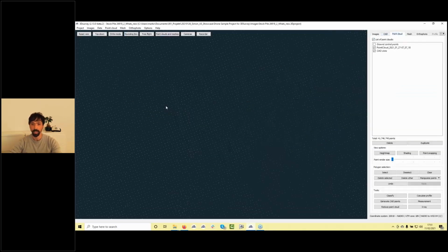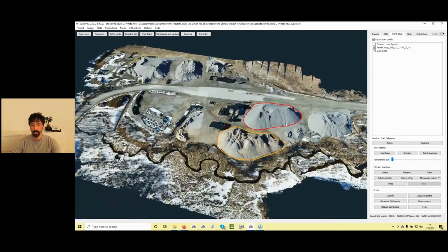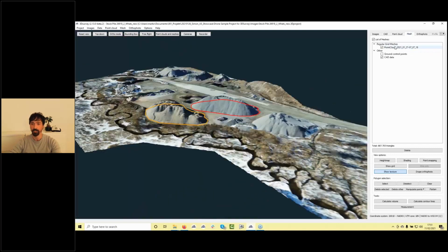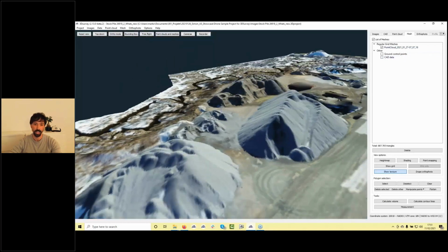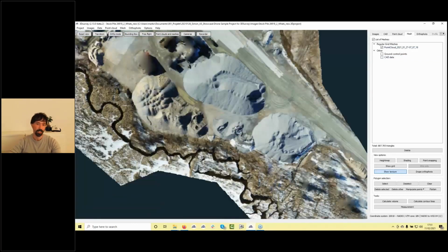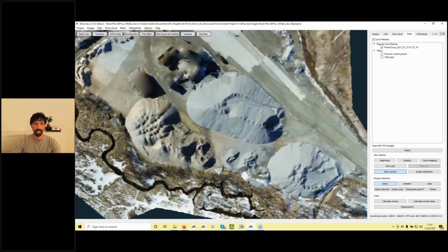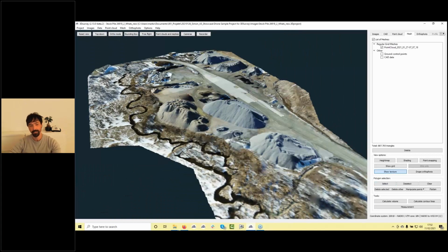Here we have a point cloud. We already see also some drawn CAD data in 3D Survey. And here we have the mesh, again a regular grid mesh, which is the best one for volume calculation. And here I would like to show you the second approach to calculate volumes. So instead of selecting your area of interest, you can actually draw CAD lines and define the volume calculation area based on this. What's the benefit of this approach?